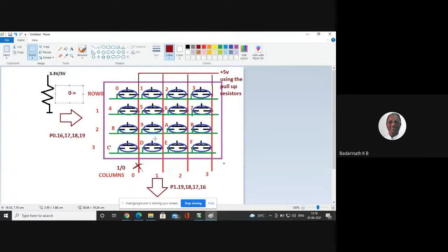Whenever you get this type of situation, you always have to use what is called lookup tables. Lookup tables are extensively used in embedded systems to convert the physical locations into the ASCII codes. In 7-segment, what had we done? A lookup table was used to convert your ASCII code to 7-segment codes. Now I'm using it to convert the physical location into the ASCII codes. The other way around.